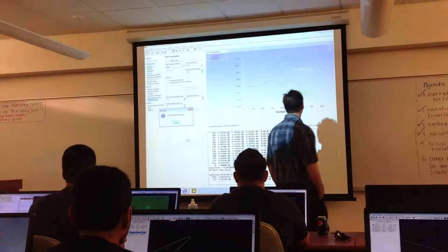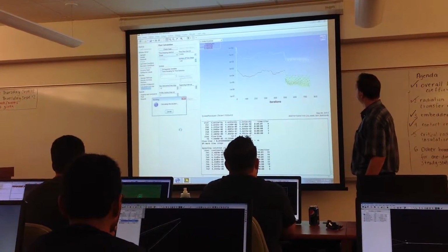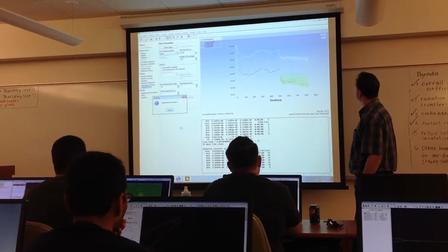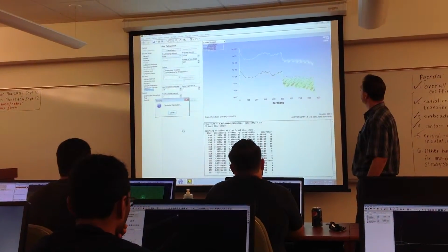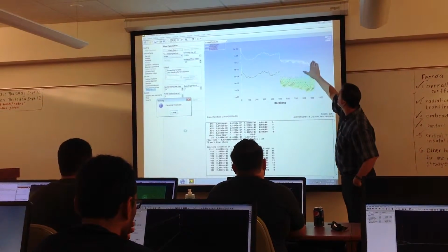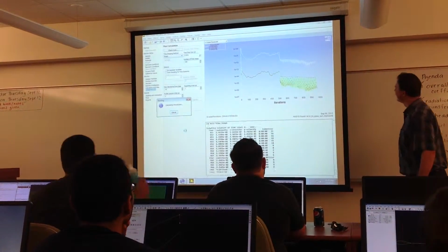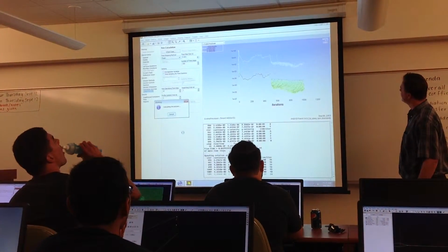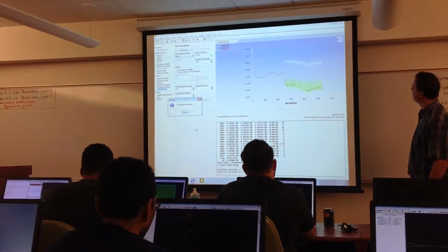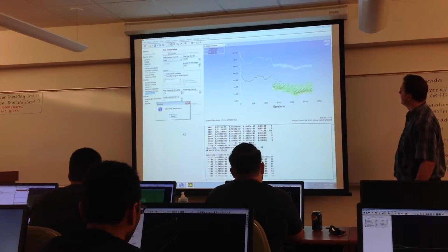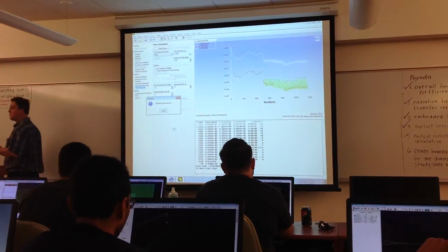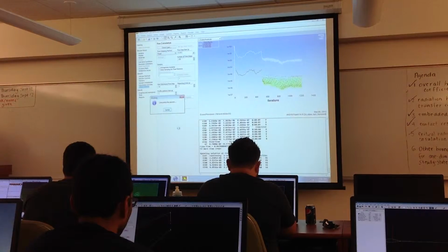The question is whether there's a trend in the residual. It's getting a little bit less unsteady. See how the residuals are dropping? Well, they were, but they're coming back up. What I'll do is bring up the lift coefficient history too, and you'll see if it's looking any better. We only ran 100 time steps.